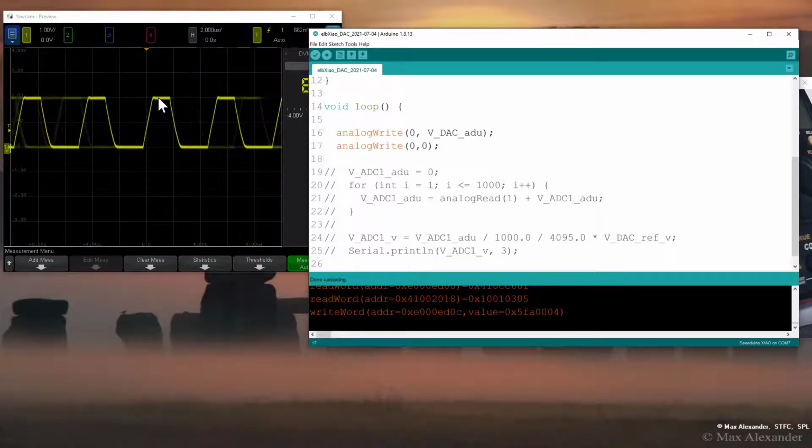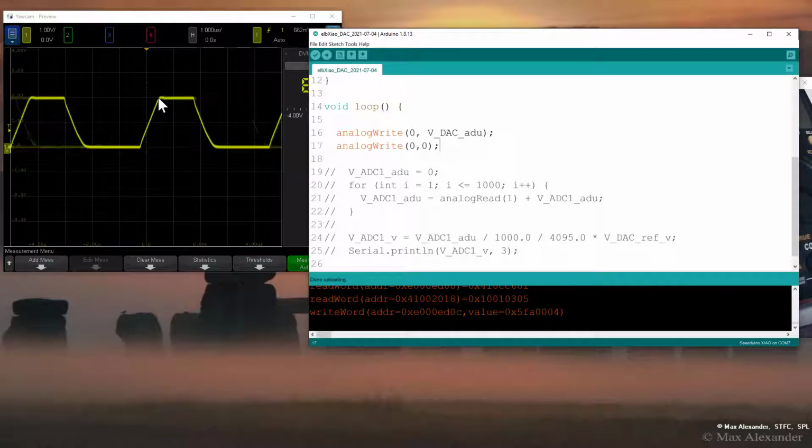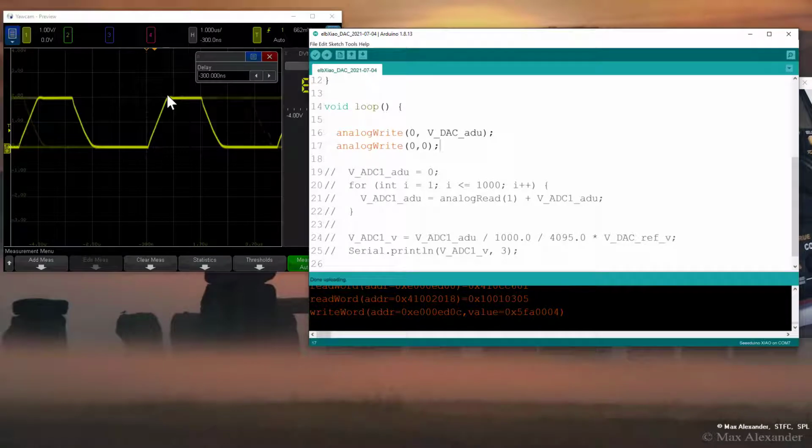And you can see here, let's see, we'll increase the scale a little bit. It's about, if we had to guess here, it's about a division. It's 2 volts. That's the voltage swing in a little under a microsecond. So it's about 2 volts per microsecond is the slew rate for the DAC. Good number to keep in mind. That says that, full scale, we want to wait at least, we turn the DAC on, turns on over here. We want to wait at least 2 microseconds before we assume that the DAC has stabilized to the final voltage. So keep that in mind if we're looking at some transient responses.